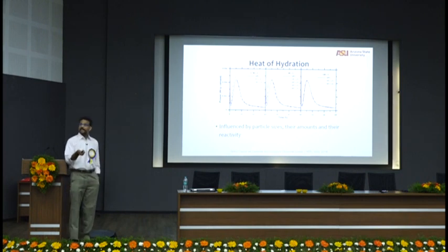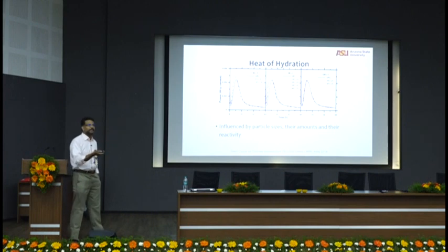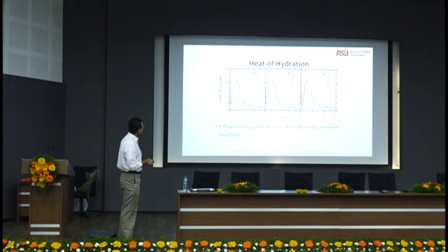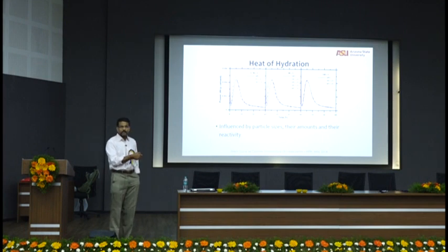So effectively, if you are worried about sustainability, I don't want to use so much cement, fair enough. Take off 10% of cement, take off 20% of cement here with a 15 micron limestone. Have I compromised anything in terms of heat? No. I've gotten exactly the same system back.